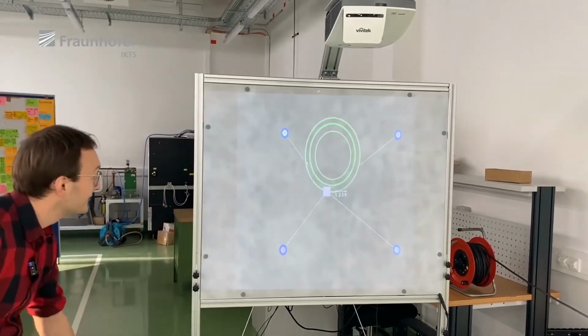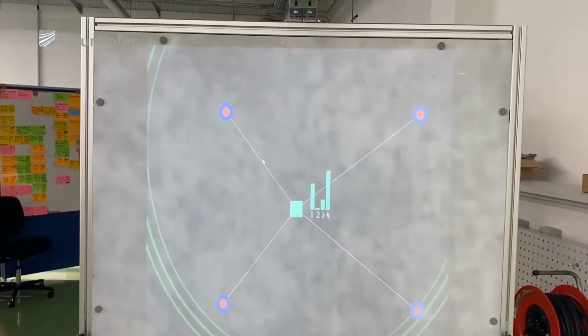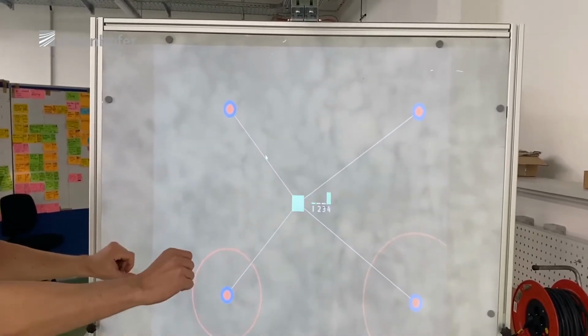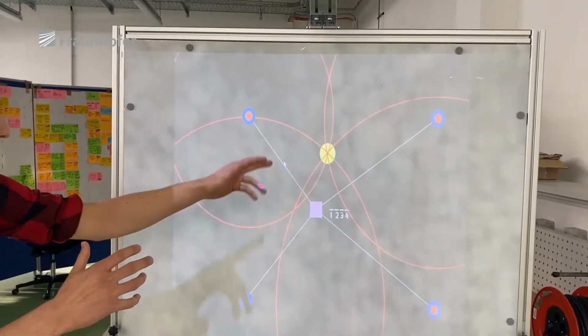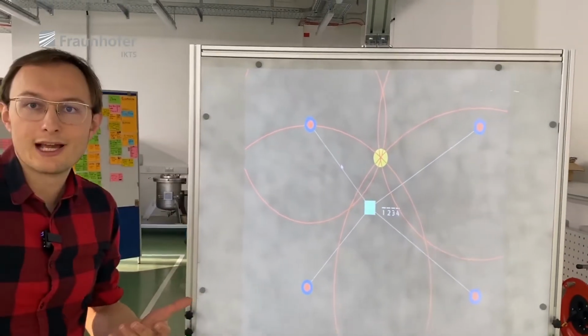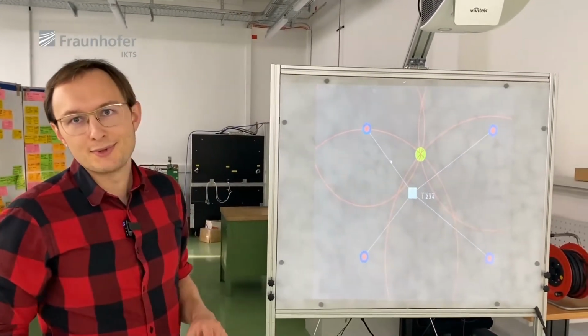And you can see the acoustic waves. They are picked up by the sensors. They measure the runtime, they communicate, and voila, they know where the crack happened. It's pretty accurate, certainly for a structure as big as that.